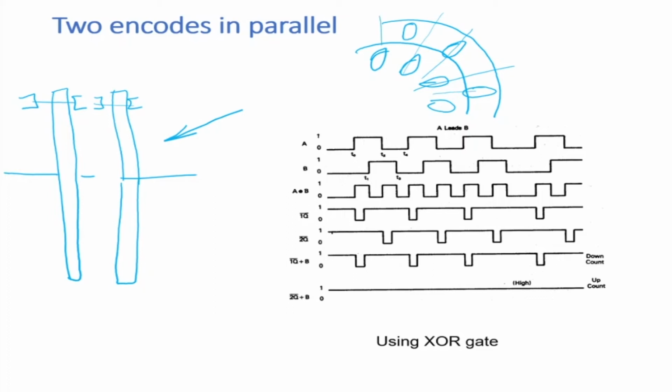Okay, now because there are two, let's call this A and let's call this B. There are two signals which are coming, 10, 10, 10, which is basically a square waveform which is shown here. So this is my signal A. It is 1 means the square top and 0 means 0. So whenever the motor is rotating or the joint is rotating, these square waveforms are going to come.